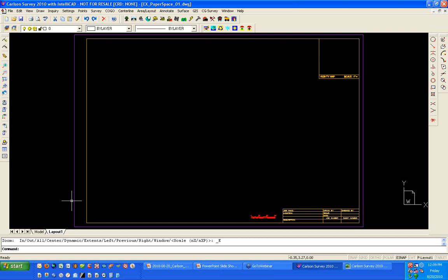There are many different ways that people go about it. I'm going to talk about what I would say is probably the most widely used method of using paper space, and that is putting a title block on one layout tab, or one paper space tab, to represent each sheet that's going to be plotted for that project.